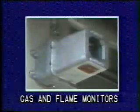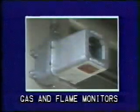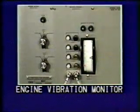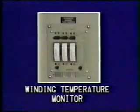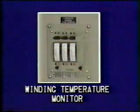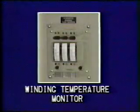The gas and flame monitors will protect the engine from explosive gases and fire. The engine vibration monitor has a warning and shutdown point to protect the package from damaging vibrations. The generator winding temperature monitor and bearing temperature monitor use RTDs in the generator to protect it from overheating.